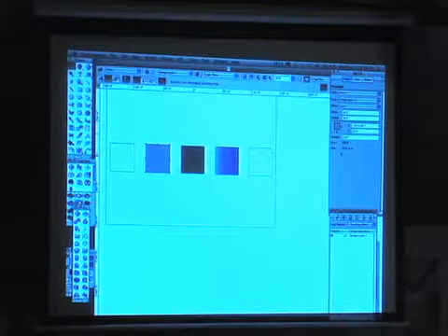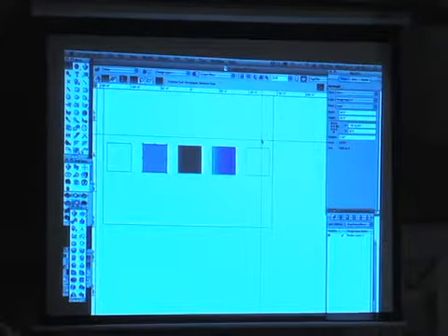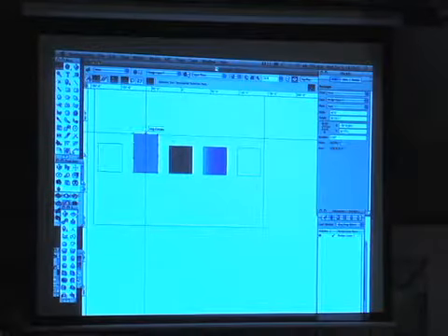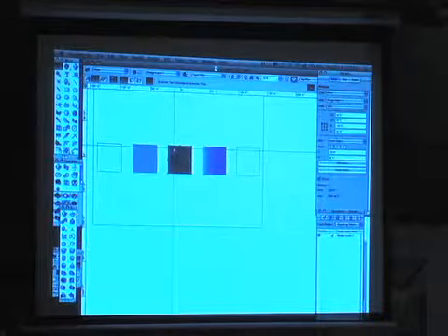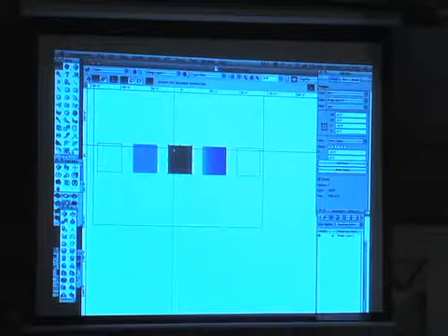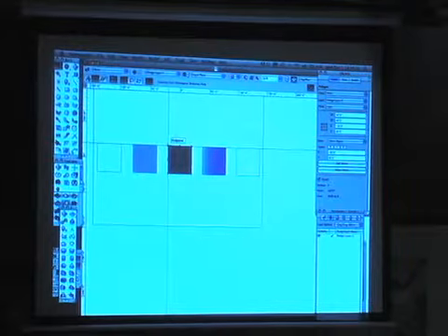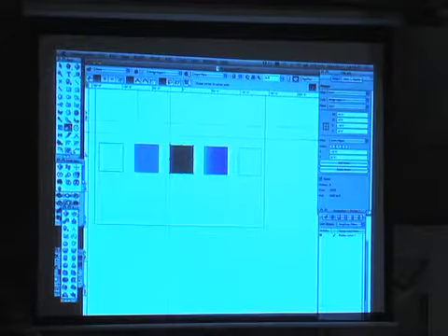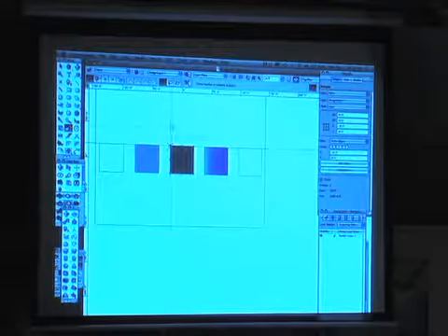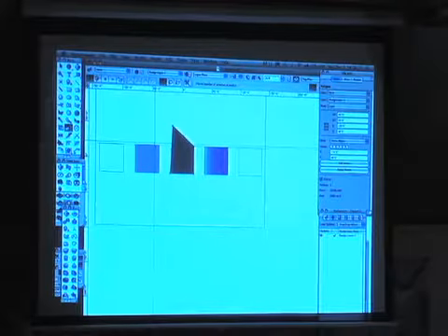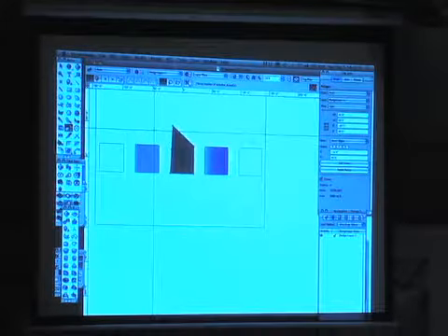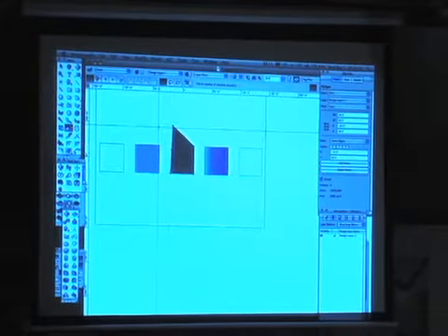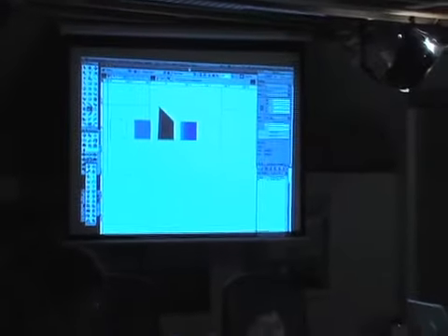But you do see over here in the object info that we get some more information on it: the area and the perimeter. Rectangles are good, but you can only adjust them in one orientation. They still remain as rectangles. This other one is a polygon, and I like polygons. Anytime you add 2 objects together, they become a polygon. The great thing about polygons is that you can adjust these vertices and get a lot more freeform shapes out of them. You can push and pull them and reshape them into different forms.